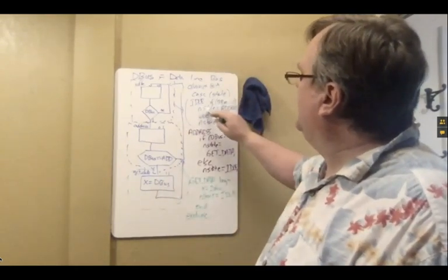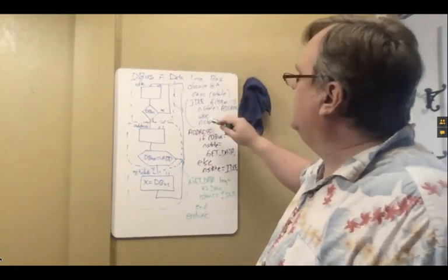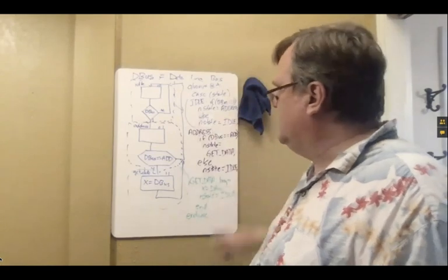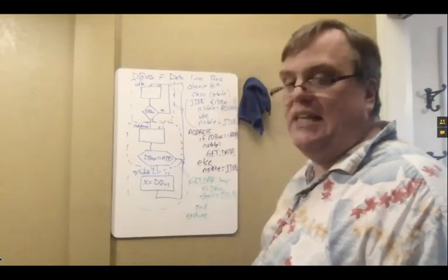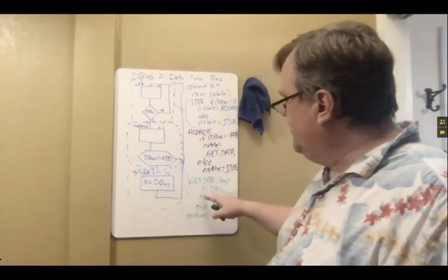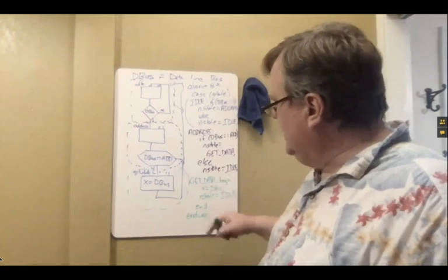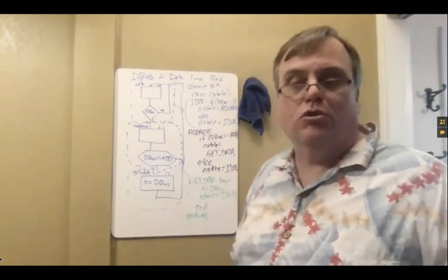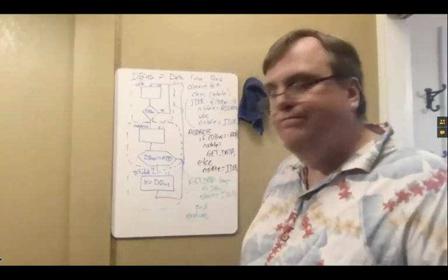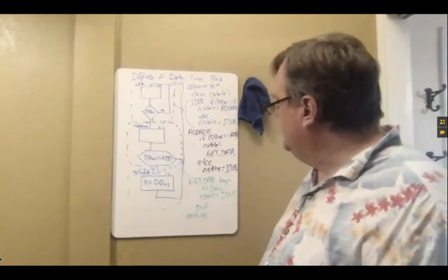On the idle, I've got an if, and this single one is in the if-then. The else also gets one statement. So again, this is one statement. Since I've got two statements, assign the value of x, assign the value of next state, those are two statements. I need a begin end, which is like open and close curly brackets. All right. I see that made sense.